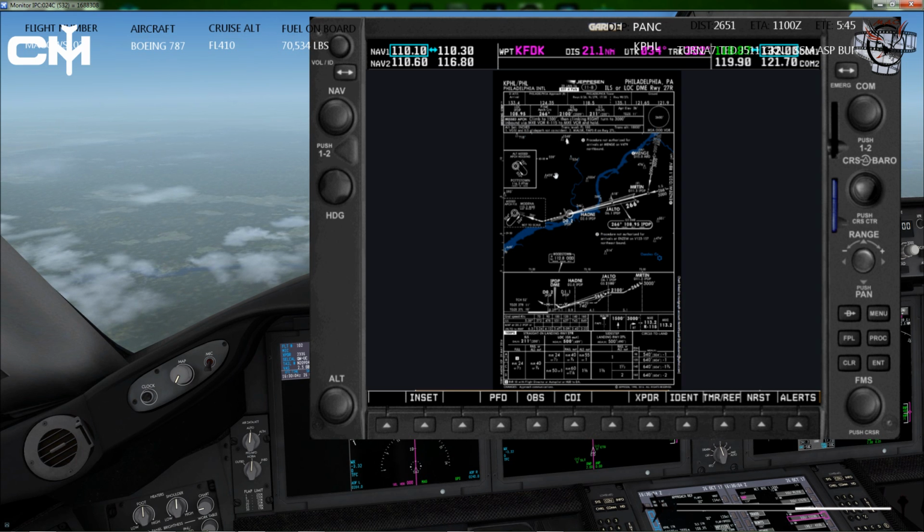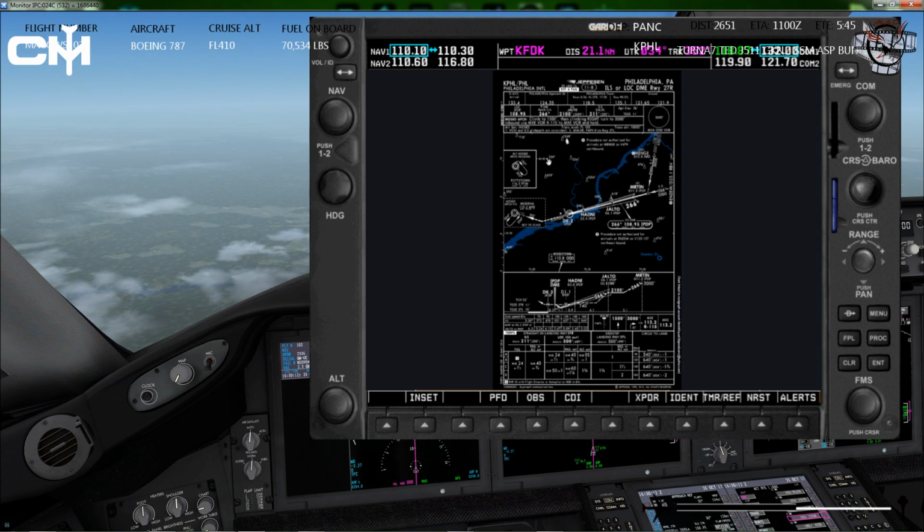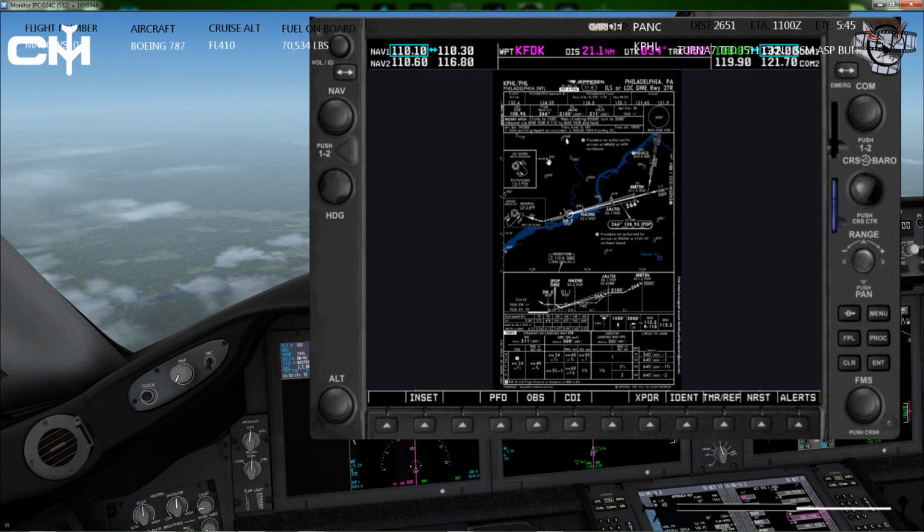Up here on our narrative, missed approach is climb to 1,500 feet, climbing right turn to 3,000 inbound. So I was close, not quite right. Inbound via the MXE VOR 115 degree radial until we hit the MXE VOR and then hold there. And that pretty much sums it up for our approach.